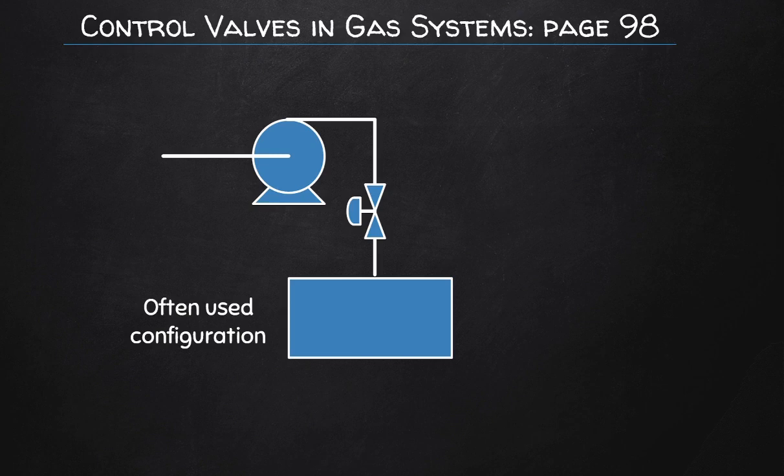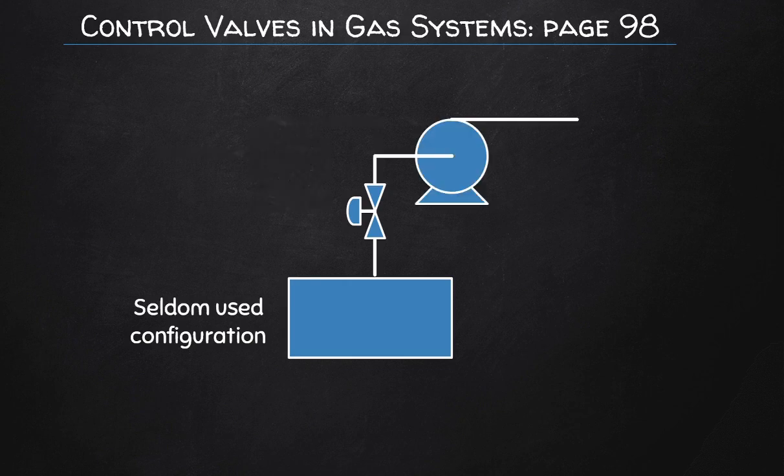Now, when you are designing a flow sheet, care must always be taken as to where the valve is going to be located. This configuration that is shown is often used for obvious reasons, where the alternative would be the following. And realize that in this case, cavitation is more likely, and this will also reduce the net positive suction head that is available for the system. As such, this configuration is usually going to be a bad choice in design unless you can't get away from it.